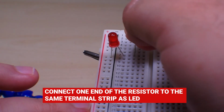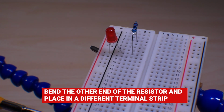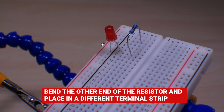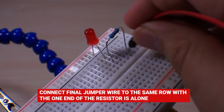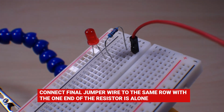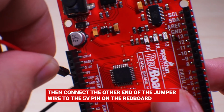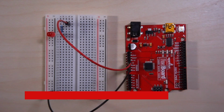The resistor will be used to regulate the current flow through your circuit. If too much current flows through your LED, it will cause the LED to burn out. Take the other end of the resistor and place it in another row. Lastly, in the terminal strip of the resistor you just inserted, take your last jumper cable and connect the end of the resistor to the 5 volts on the breadboard.